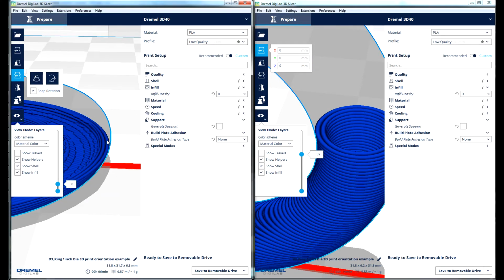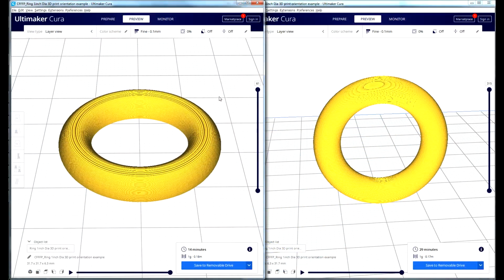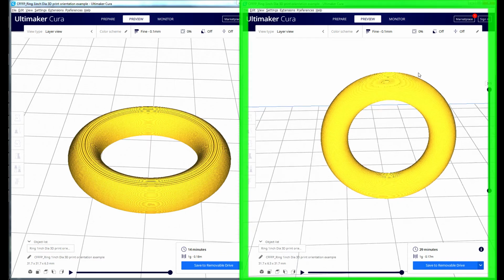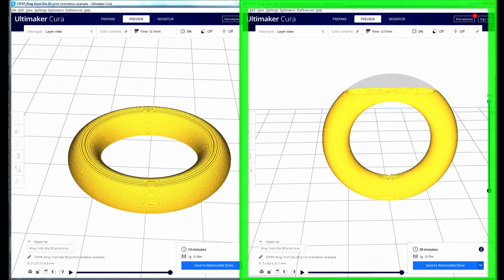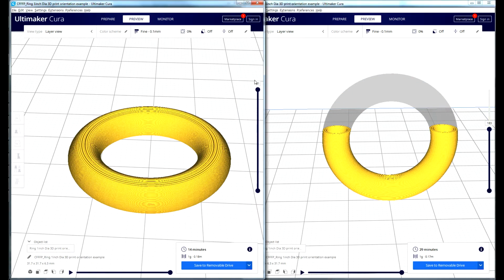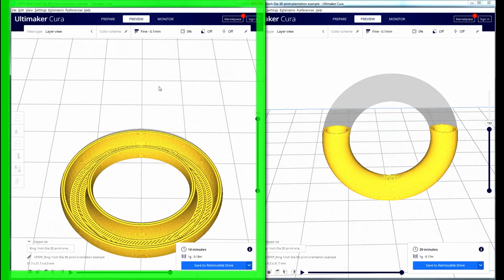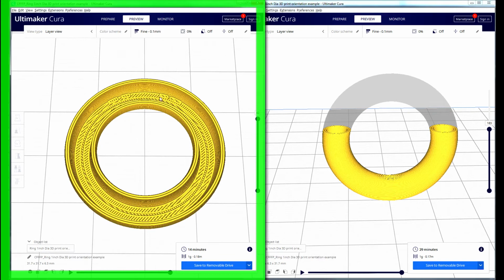But why? Looking at the cross-section of each orientation shows how the part is built. On the right, pulling this ring will result in a break between the printed layers. This principle is the same when you split wood along the grain. The orientation on the left takes advantage of a continuous extrusion of filament.